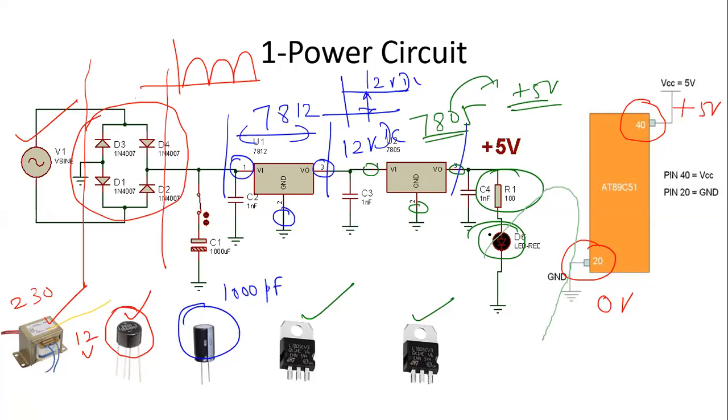So if the power circuit is working normally, and if the circuit delivers constant 5 volt at the output, this power LED will illuminate and tell you that there is power in your board. So that is a quick and easy way of identifying whether a particular electronic board is powered or not. So it is always customary to end your power circuit with a power indication LED, current limited by a resistor, which is what we have done here also. So there is nothing special here.